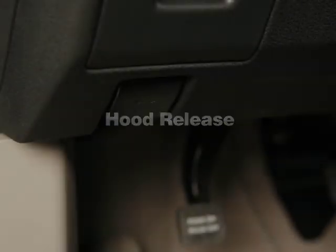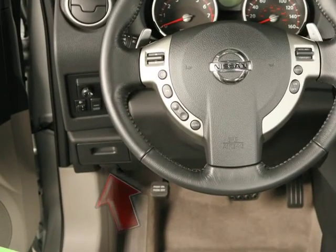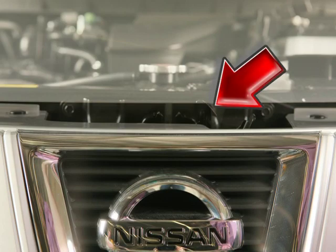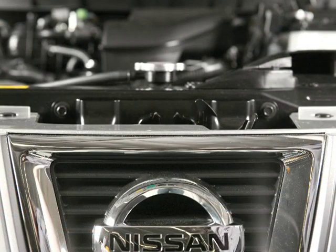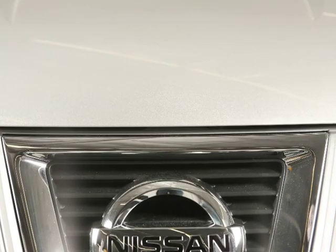Hood release. To open the hood, pull this hood release handle located below the driver's side instrument panel. The hood will spring up slightly. Outside the vehicle, lift this lever at the front of the hood as shown. Then pull the support rod down from the underside of the hood and insert into this slot. When closing the hood, lower to approximately 12 inches above the latch and release. Before driving, look to see that it is latched firmly.